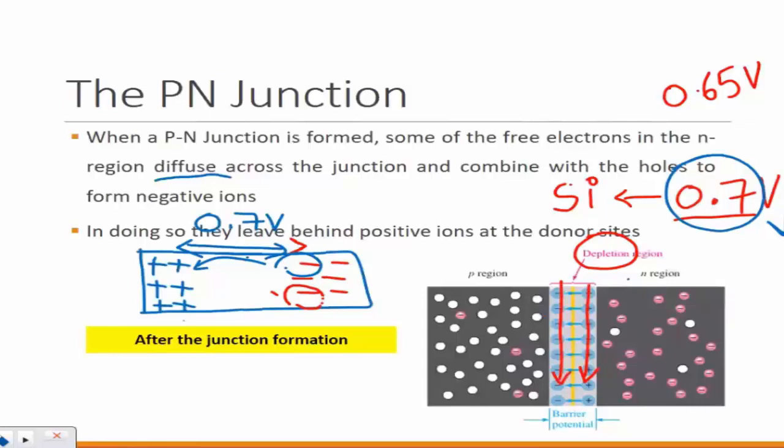Again, there are some limitations to how much it can handle. Because if you apply too much voltage, the amount of current through the junction increases. So eventually the heat increases. That may damage the diode. But some diodes can handle 50 volts. The ones in our power supplies, like chargers, have 400 volts.